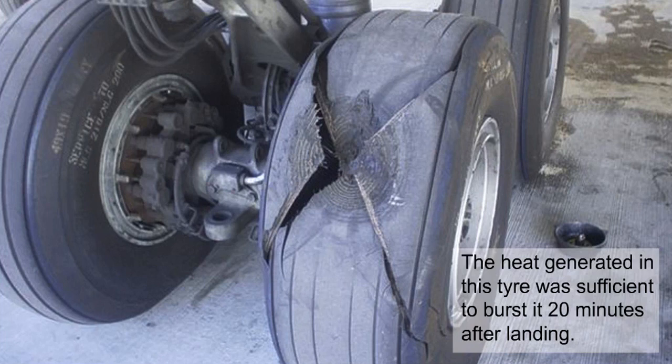In the event that a tyre is hydroplaning and the available friction is insufficient to rotate the wheel, a lot of heat will be generated converting the ice or water into steam. The converted cushion of steam lifts the tyre off the runway, eliminating tyre-to-surface contact, and the steam heat reverts the rubber to a black gummy deposit on the runway, causing the wheel to skid, thus eliminating braking effectiveness and directional control.